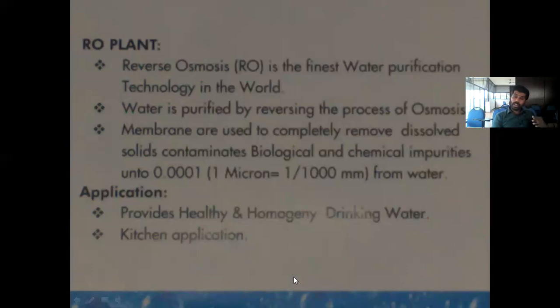Then even for rainwater we have filters. We can construct filters ourselves by placing sand, pebbles, carbon, charcoal like that. So we can make a filter by ourselves also, by using materials like sand, quartz sand, and activated carbon. Okay, all those things we can use.